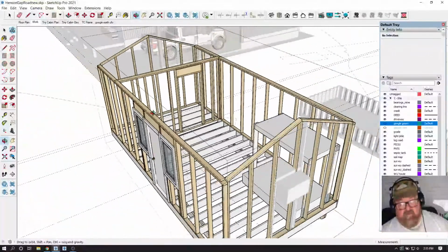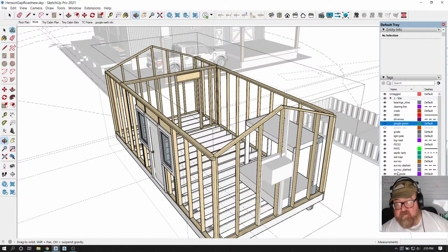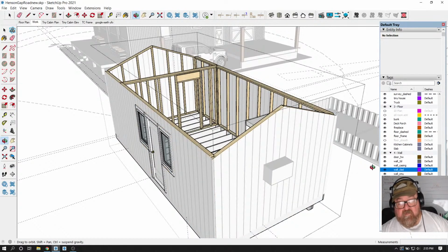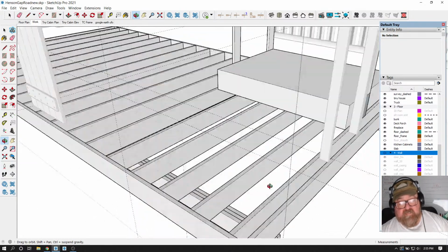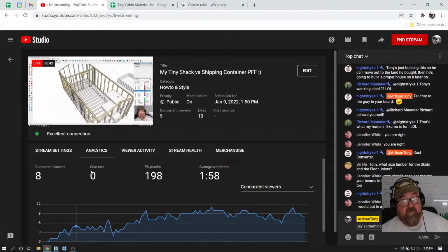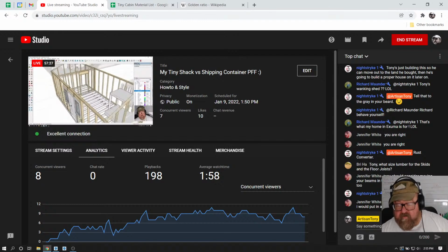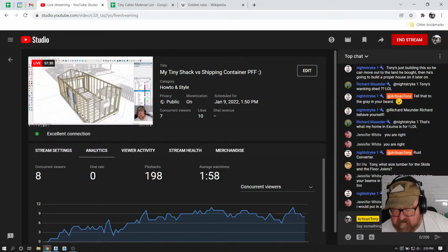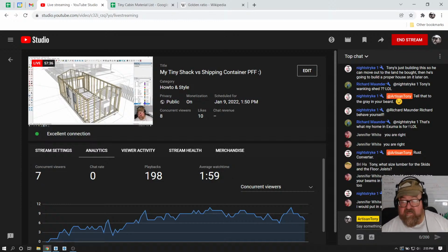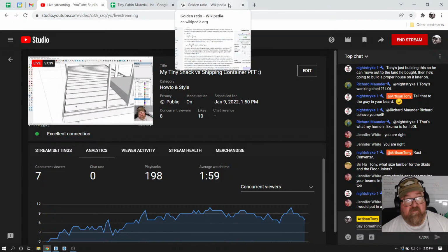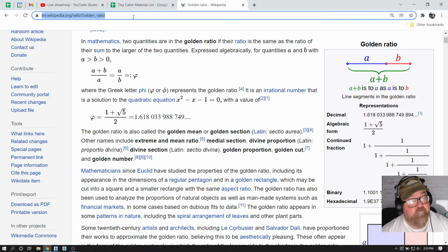But I got distracted, didn't I? I was going to tell you the walls. The floor joists are 2x8 on 16-inch centers. If you're going to skid this around, I would put it on metal skids. Most likely I'm not going to skid it around. I have a friend who owns a crane company. You may have missed it earlier. Now you messed me up. I was going to do Southern Pine.